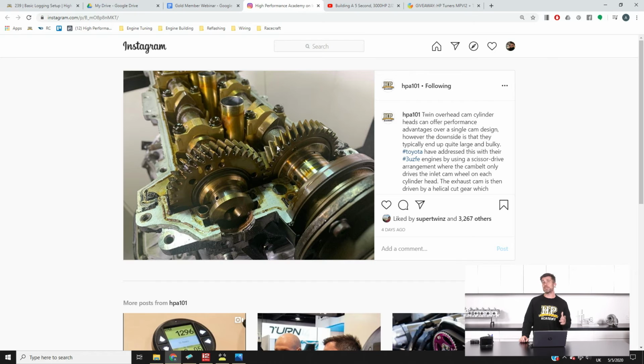The problem is that if you just simply take those cams out, what's going to happen is that spring-loaded section is going to spring as far as it can. And while that's not unrecoverable, if you don't know that's happening, you go and put it back together, it's not going to work how it should. The spring-loaded mechanism won't be taking out that lash, and you end up with an engine that sounds like it's run a bearing sitting there at idle.